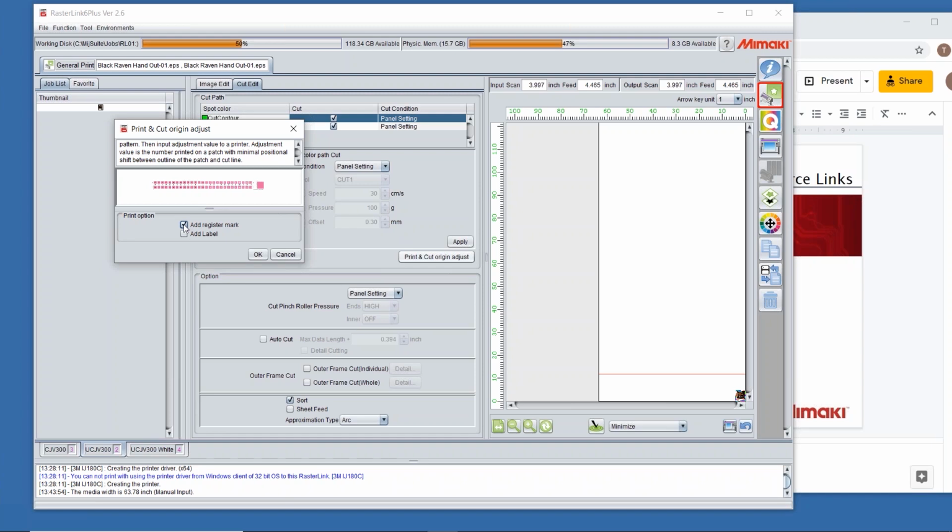It does depend on the digital sensor we use to pick up the mark being, number one, clean, and two, able to pick up the marks on there. If you're in a situation where you're running it and you're seeing offsets that are greater than about 0.5 millimeter, we would like you to reach out to a call center and we can walk you through some steps.